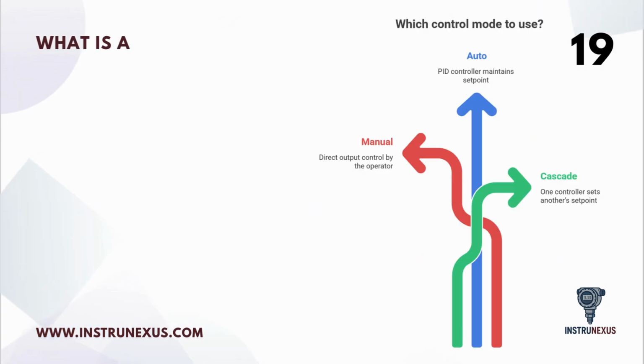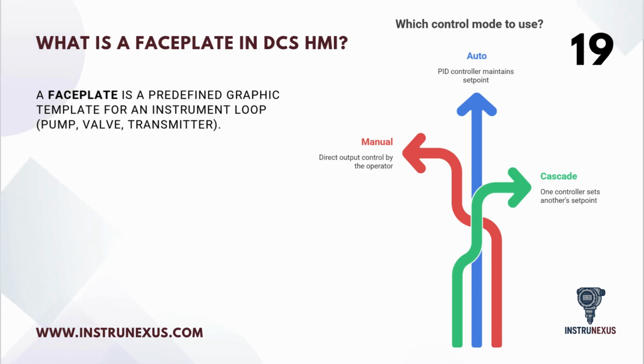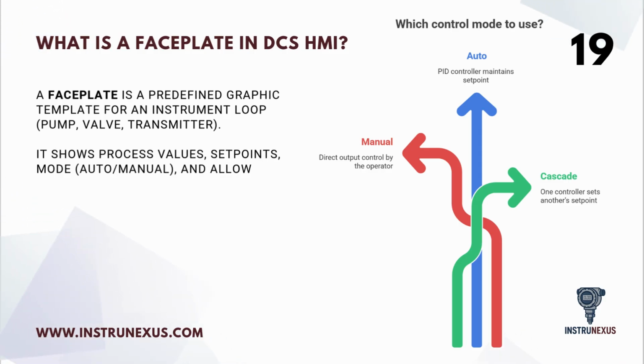What is a faceplate in DCS HMI? A faceplate is a predefined graphic template for an instrument loop, pump, valve, transmitter. It shows process values, set points, mode, auto/manual, and allows operator interaction.